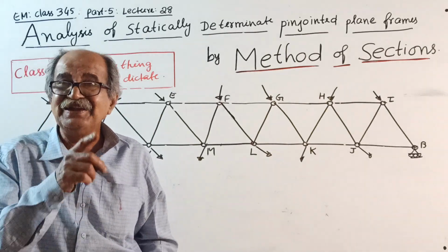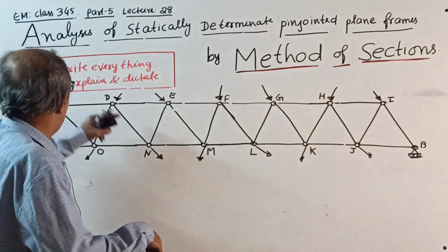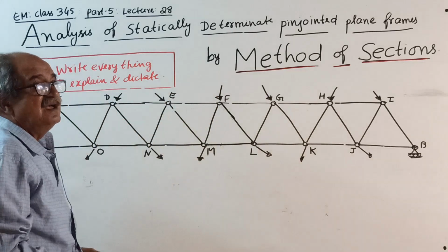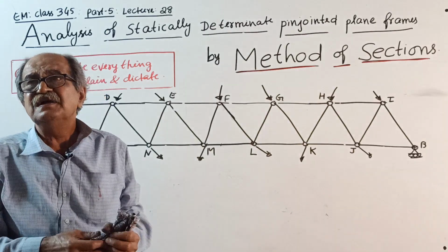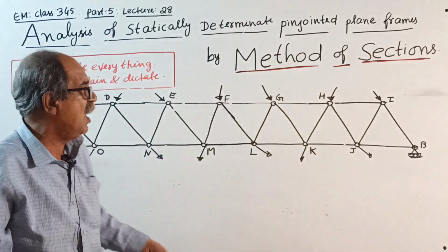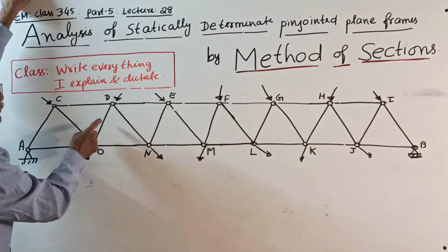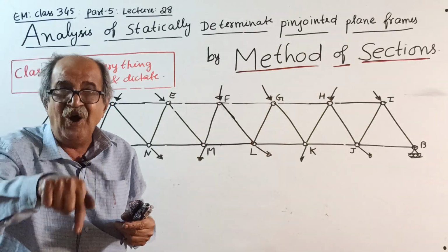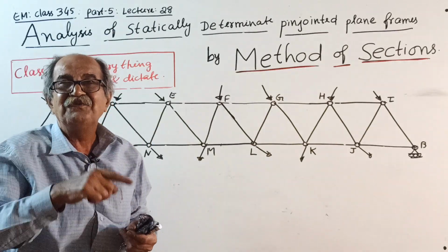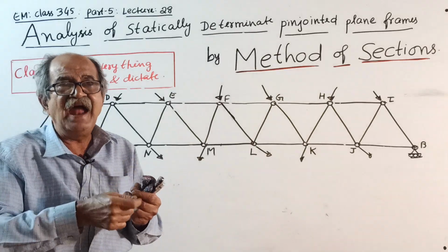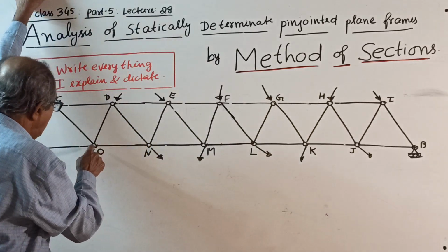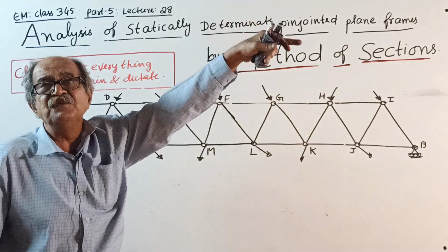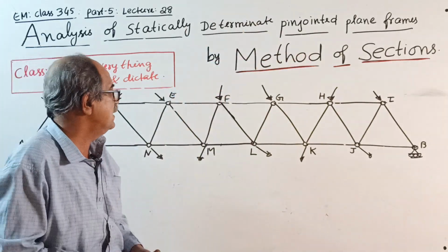External forces acting on that joint are either directly applied external forces, or if that joint is a support, the reaction from the support, and also the external forces acting on the joint from whichever members are connected to that joint. But external forces acting on the joint from that member later will become the axial force for the member. That is later.